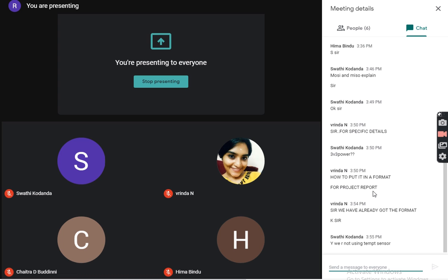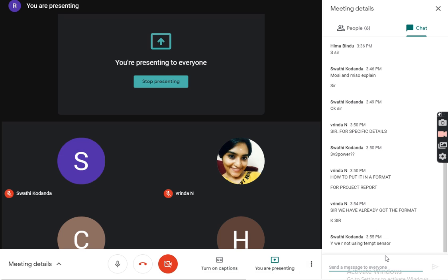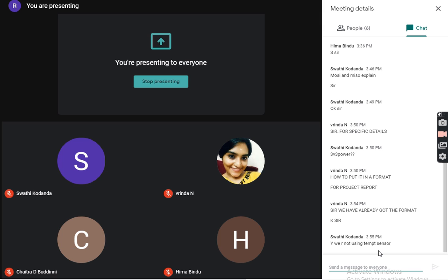Even what I am suggesting to you is, yeah, we can use the temperature sensor. If we use a temperature sensor, then we have to go for MCP 3008. We have to change to that because one extra ADC will be needed. So 4 pins are already busy, so we can't use MCP 3004. We can use MCP 3008. But we can't use 3004 now. We have to use 3008.